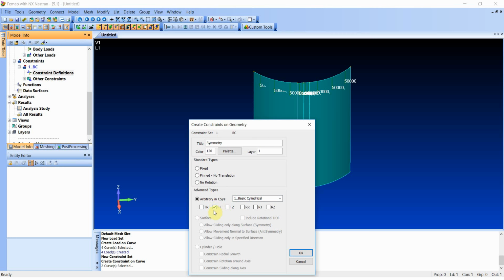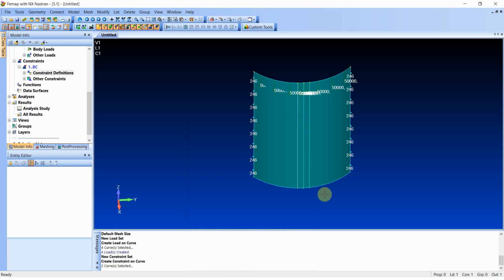I can simply say this is on the angular part of cylindrical coordinates, and this way I don't have to define any local coordinate systems to do so. So it's nice, and also some solvers do not like when you mismatch coordinate systems between loads and boundary conditions. This is why I used cylindrical coordinate system everywhere, even though rectangular would be just as good. And it's done.